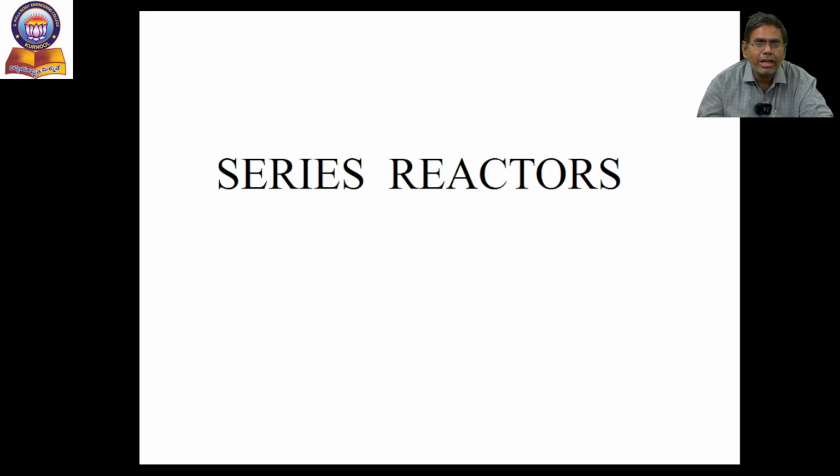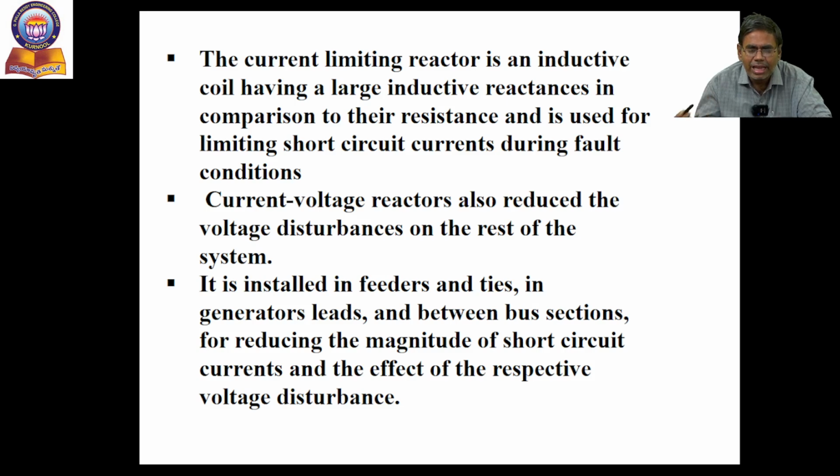One more important topic is series reactors. To limit the short circuit current to particular values, we go for reactors. The reactors are classified into three types. One is a generator reactor, another is a feeder reactor, and the third is a busbar reactor.